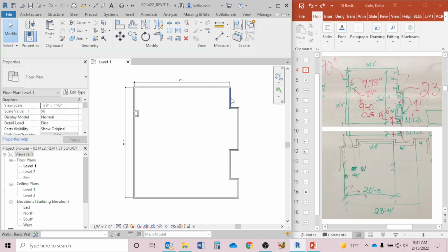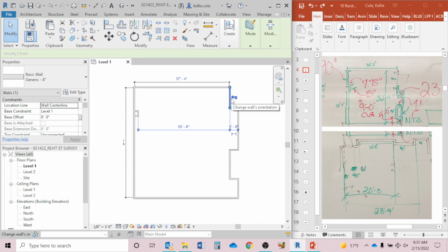That's okay. I'm going to select this wall. I'm going to touch the dimension. So the wall was selected first. Touch the black colored dimension that turned blue. Type in 33 feet 2 inches. Enter. Wow. So I've drawn this really too large.